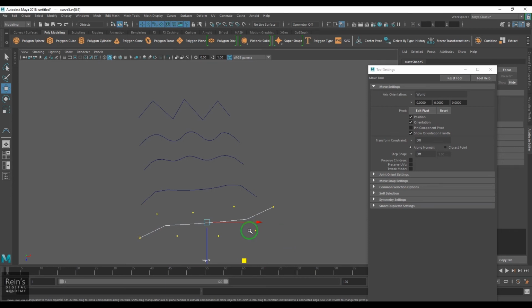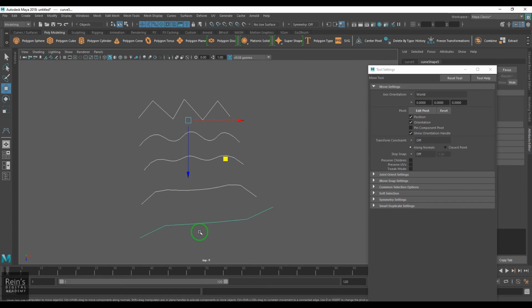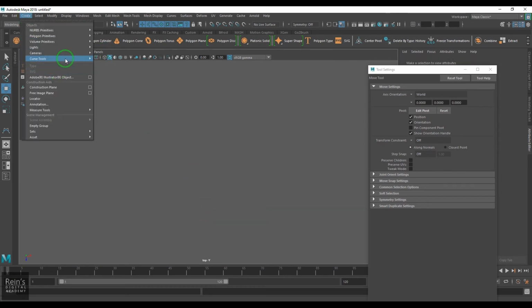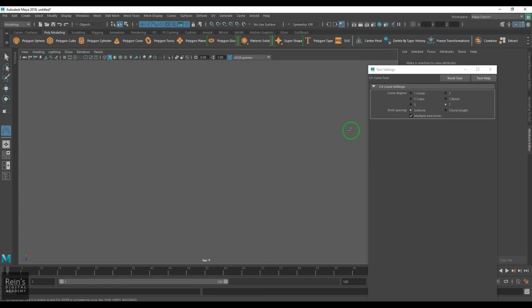In 7 degree you get more points, but the difference in the position of the points does not affect the curve much. It is quite stable, whereas in a lower degree a small change here and there changes the shape of the curve. So Maya generally recommends a 3-degree curve versus a 1-degree curve, because a 1-degree curve gives me a straight line and a 3 degree gives me a spline.